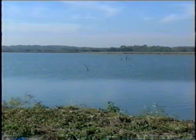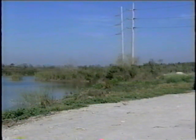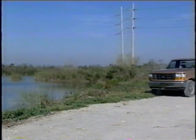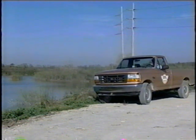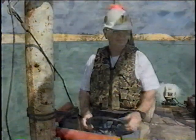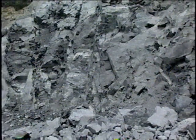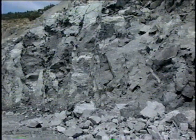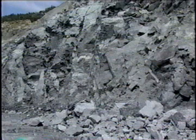Numerous other hazards can exist in the mining environment. Look for hazards such as employees working around the water who may drive a vehicle too close to the edge of a settling basin or pond, running the risk of rollover into the water. Do employees work on dredges or boats without personal flotation devices? Where are high walls that may be unstable, with employees working or walking below too close, placing themselves in danger?